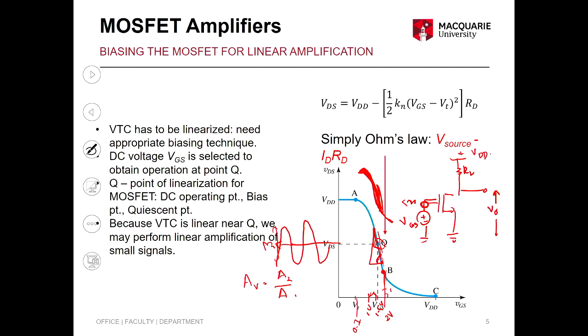But that means when you don't use a circuit, you still use that ID. When you're idling, because you still provide the bias, you are using more current, right? So more power usage pretty much. So what do you think your mobile phones or watches have to have? The lowest power consumption when they are not in use. So they tend to be biased at a very low VGS. So they might be biased here if they're not power amplifiers. Obviously you won't have power amplifiers here. Only your transmitters in the phone, because you need a high power amplifier to transmit signal.